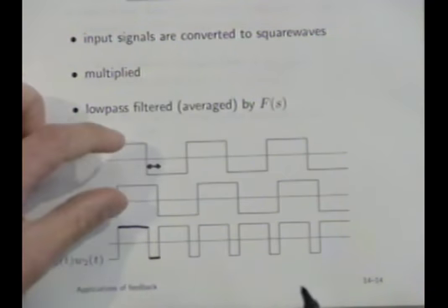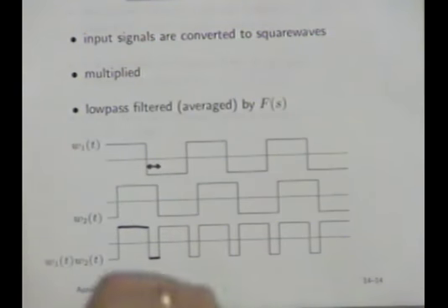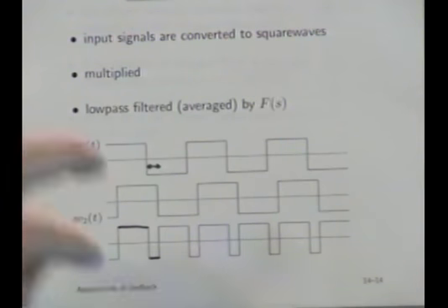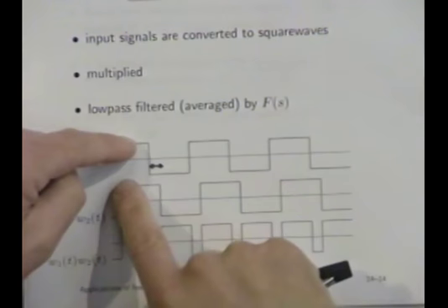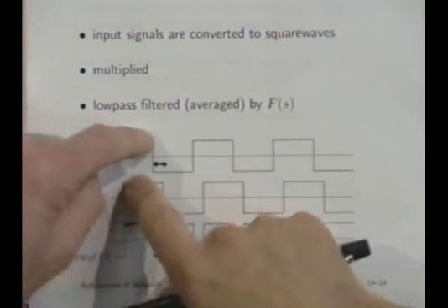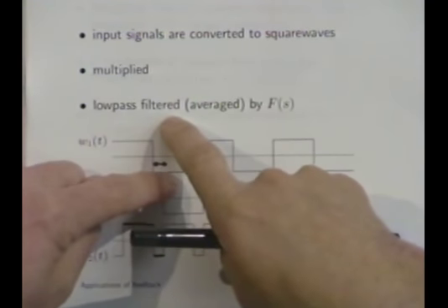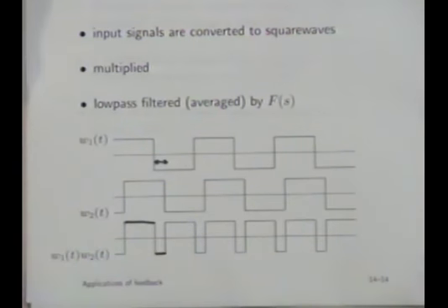What if they were absolutely anti-phase, so they were locked at 180 degrees apart from each other? If they're 180 degrees phase shifted, what do these things look like then? What does the signal look like? It's just minus 1. Because this guy's 1, this one's minus 1, and at the very same time they switch, and one becomes 1, the other becomes minus 1, and the product is always minus 1.